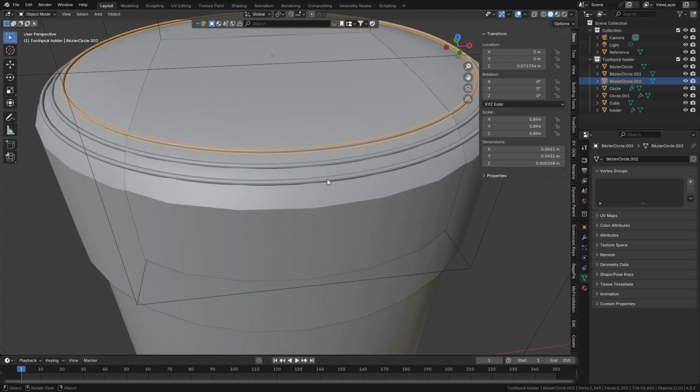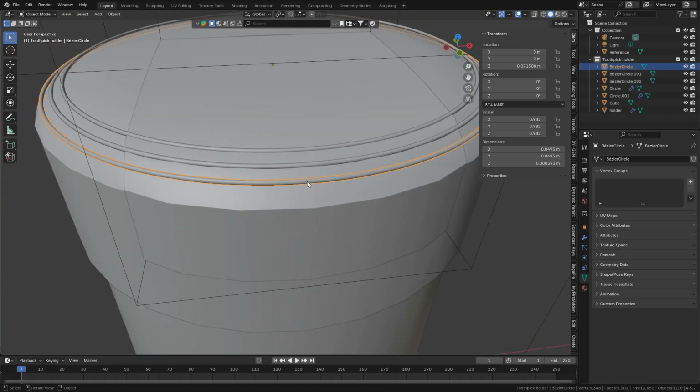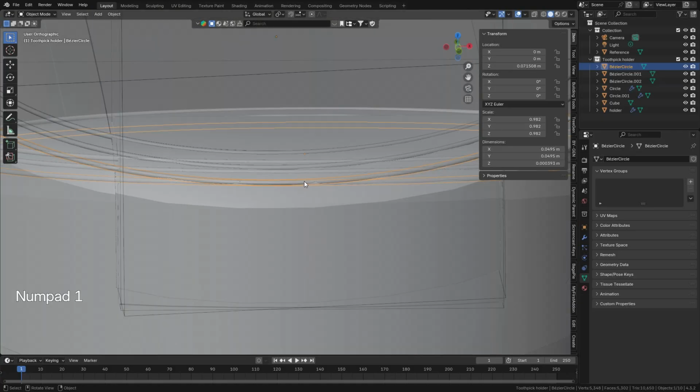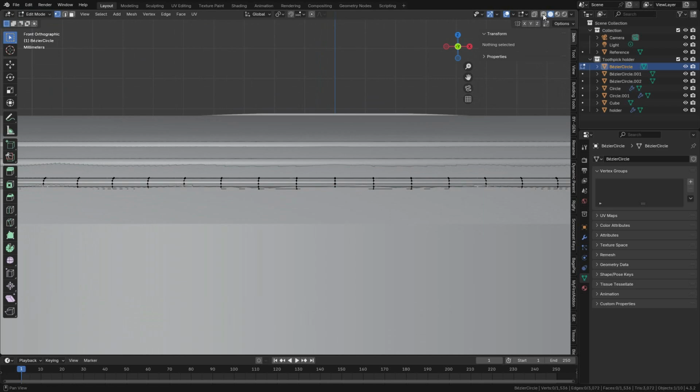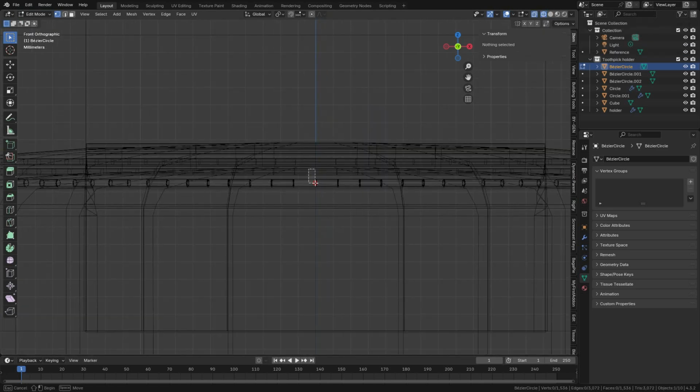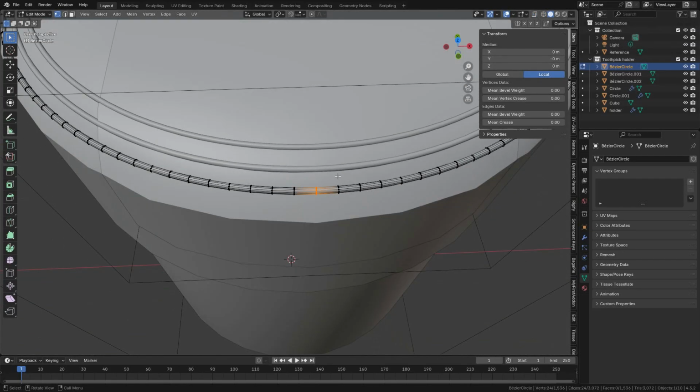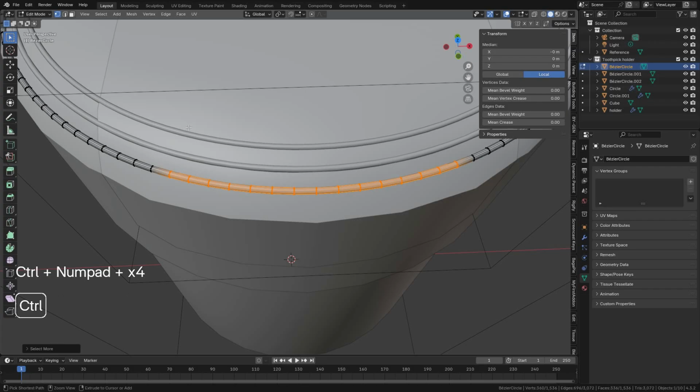So we're going to take our time doing this one by one. We start with this one here. Press 1, go to edit mode. Make sure you're in wireframe mode. Select this center which goes right through the Z. Go to solid mode. Then hit the keys Ctrl and plus to expand our selection. You do that again till the vertices meet near this edge. So do that.